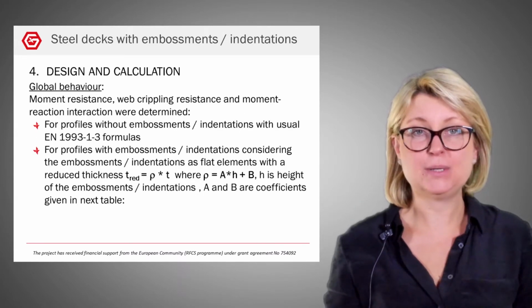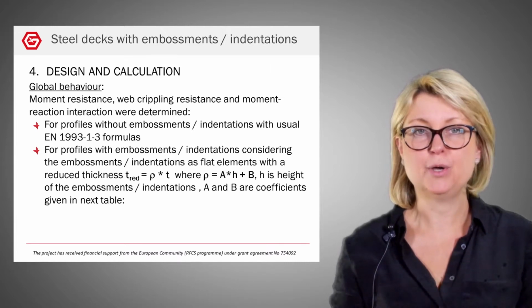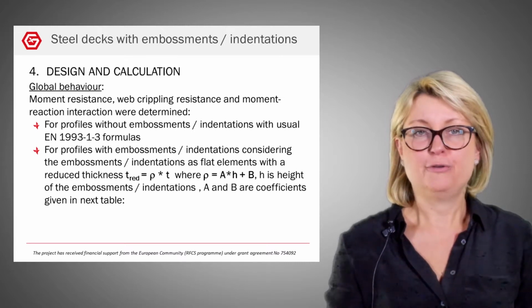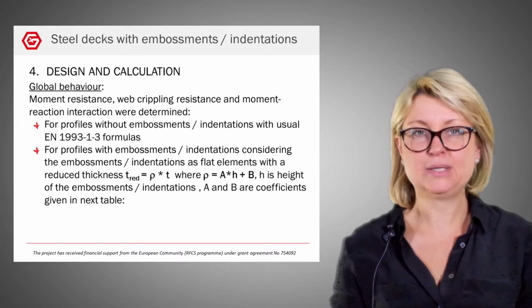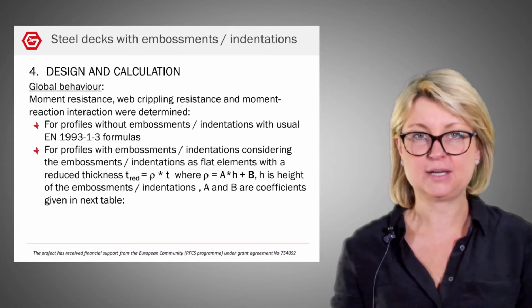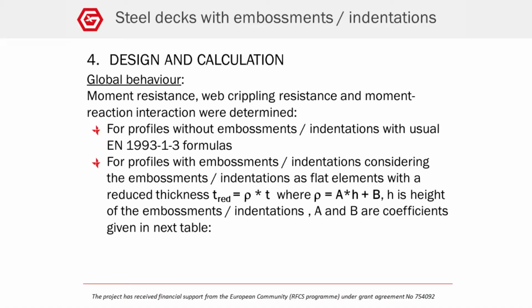The next step in our scientific process was to come up with a calculation method for moment resistance, web crippling resistance, and moment resistance interaction. For profiles without embossments and indentations, resistances were calculated according to Eurocode 3 1-3. For profiles with embossments and indentations, resistances were calculated with Eurocode 3 1-3, but by considering the embossments and indentations as flat elements with a reduced thickness